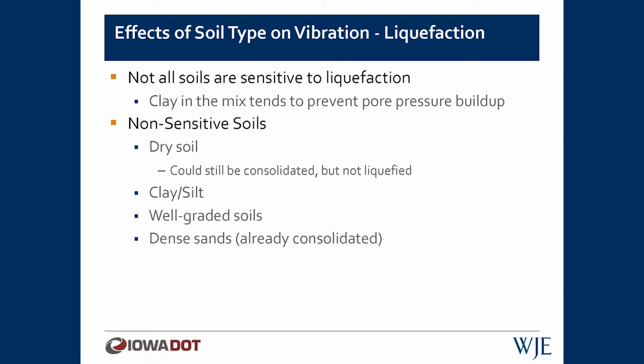Possibly what could happen with vibrations on a wet sand that's not totally saturated is that the vibrations may tend to drive the water off the grains and cause them to settle to a lower point, in which case the saturated water level may rise, and that soil might become sensitive. Now, dry soil could be consolidated by introducing dynamic vibrations, like dynamic compaction, but it's not necessarily sensitive to liquefaction.